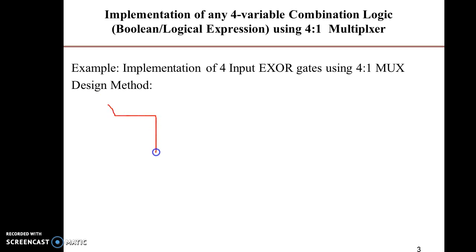So here I can draw one block to generate the logic corresponding to the I0 data input pin. Here the variables A and B are eliminated, and I am going to find the logic corresponding to the C and D variables.